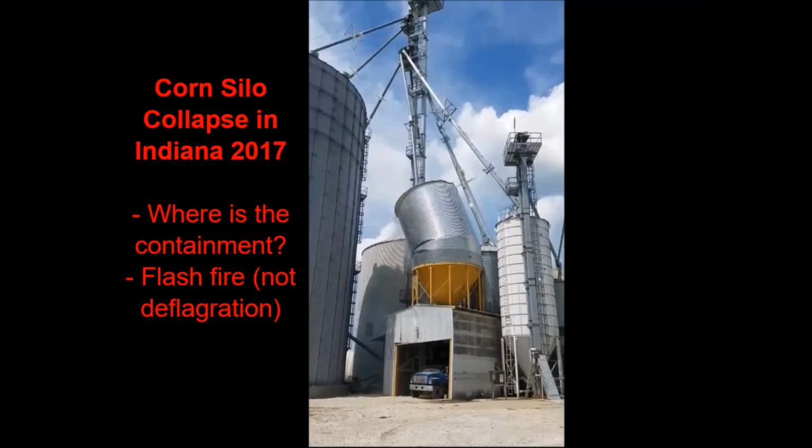First, there was a video that I found that is very telling of what can occur even outdoors, where normally in a combustible dust scenario, you look for the normal fire triangle plus a couple of other things. One is containment and the other is dispersion. And the point here is even without the containment, you can still have a flash fire that is highly hazardous.